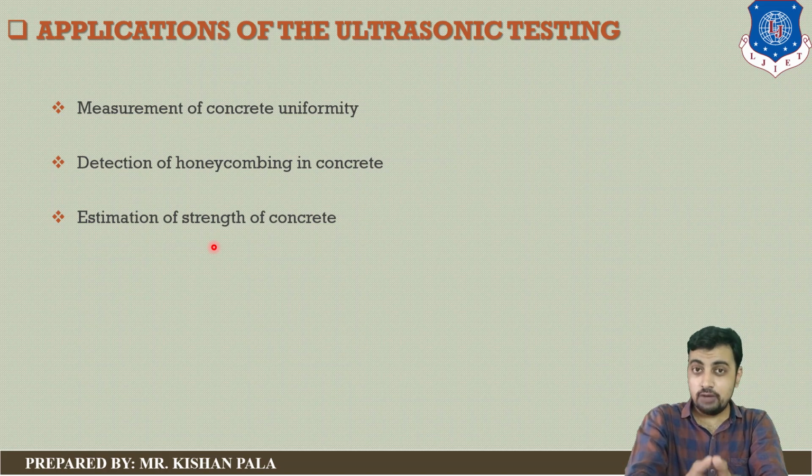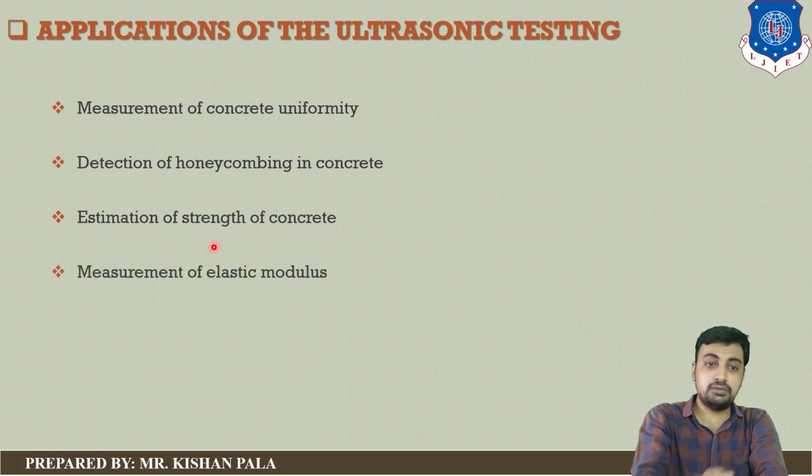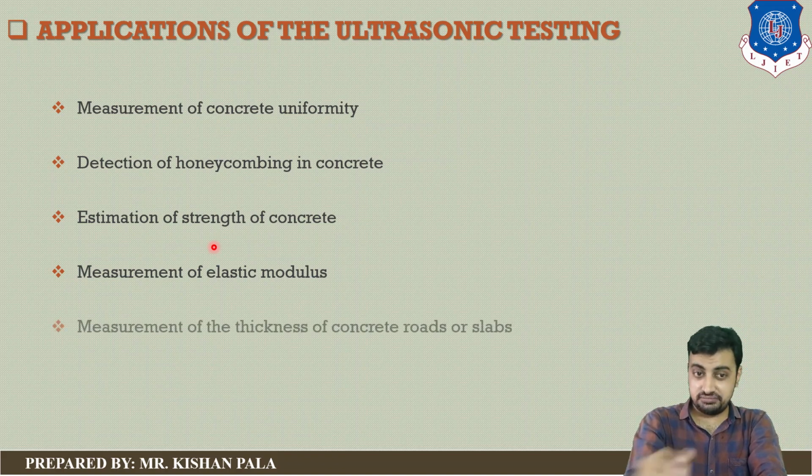And next one is estimation of the strength of the concrete. With an increase in the ultrasonic velocity, there is an increase in the quality of the concrete mass. A higher velocity will give you a higher strength of the concrete mass, particularly compressive strength. Next is measurement of the elastic modulus, which is also possible with this test.